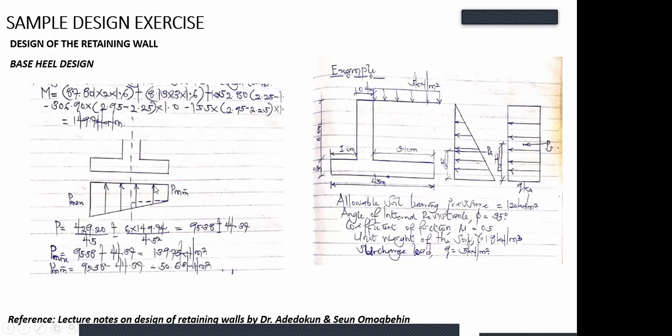Now, let's move on. If we want to design, we've gotten our P. This is your pressure distribution. So the ultimate limit base pressure will be used to compute the design moments. How are we going to generate our design moments from our base pressure? Note that the U is just a segment of the base. As such, the pressure distribution at the base of the wall must be accurately sectioned. So this gamma is just saying that you are taking just 3.1 out of 4.5, because that is your U dimension.